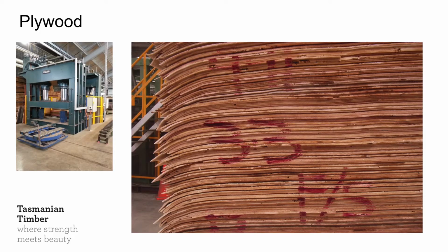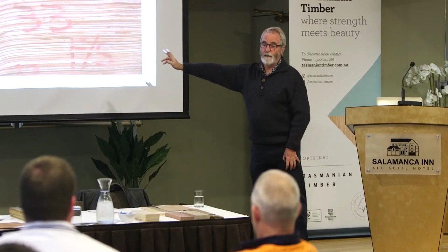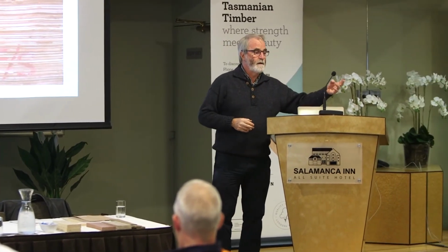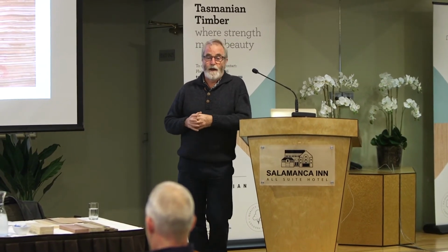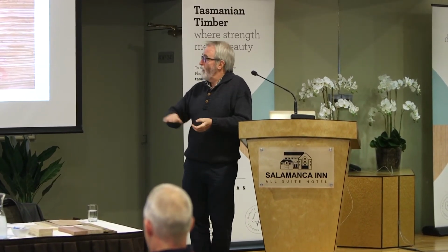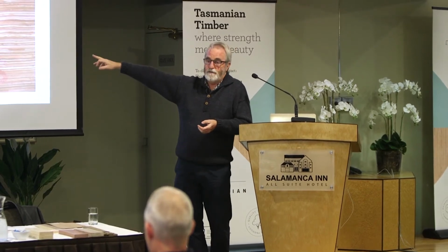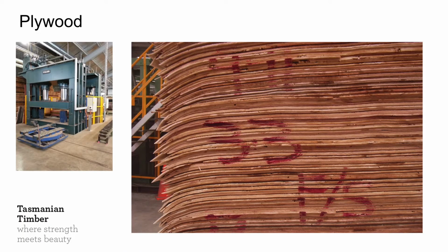Now I don't have any samples of the plywood with me, but this is peeled oak veneer that's peeled at Taran's mills in either the south or the north of the state. Taran has then put in a plywood pressing line, and that's a part of it there on the left. So when you want to make plywood, of course, you've got to peel it first. It looks like this. You've then got to dry it. It's graded. You arrange it.